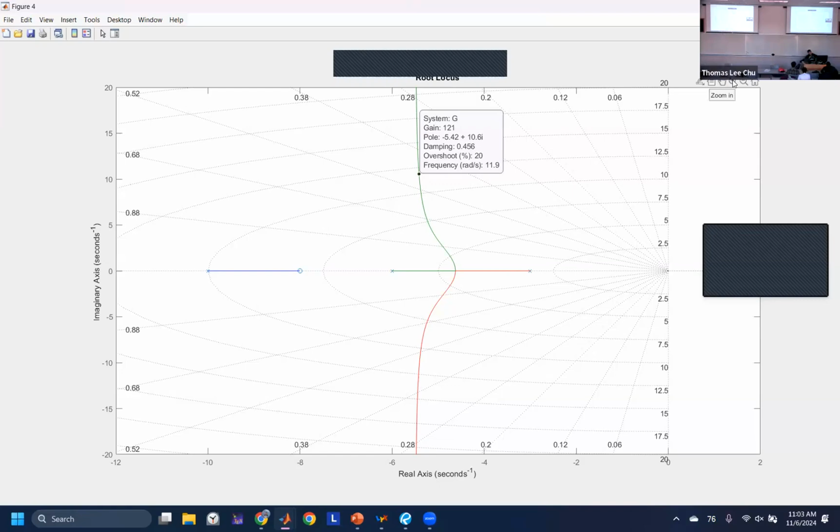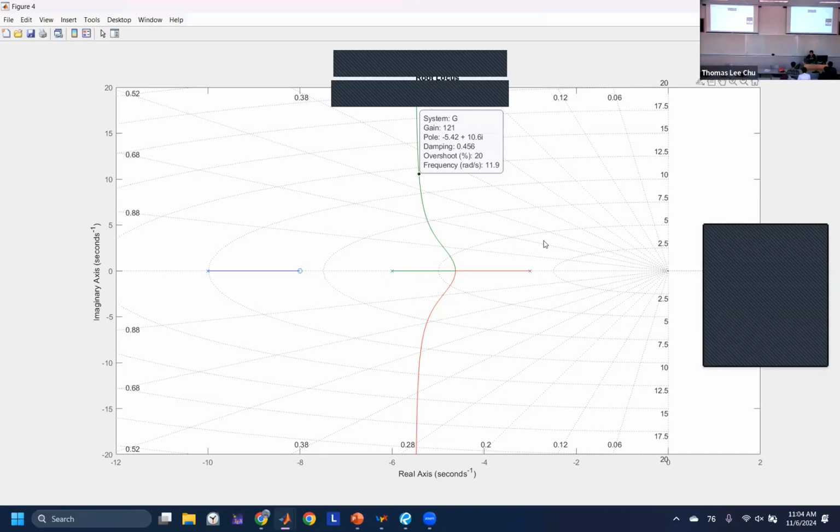When I look at a root locus, maybe it's the way I program my brain, but I can see that there are 3 poles and 1 zero. So I automatically calculate in my head asymptotes at -90 degrees and 90 degrees, because we have 3 poles minus 1 zero, so that's 2. And then we do odd multiples of 180 divided by 2, and we get 2 unique angles of 90 and -90 degrees.